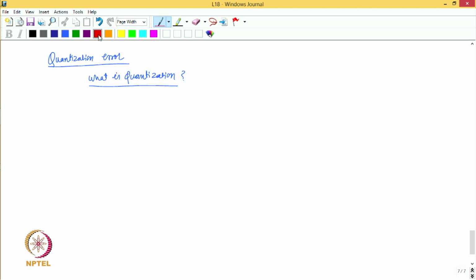So, we can represent the process in this manner, that we have the signal x_c(t), which is the continuous signal we are trying to analyze. And then of course, we have anti-aliasing filter, which basically gives a filtered signal, and then the signal is sent to A to D converter, in which the first step is discretization.